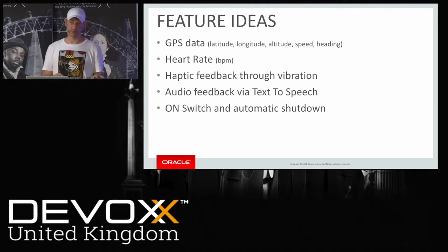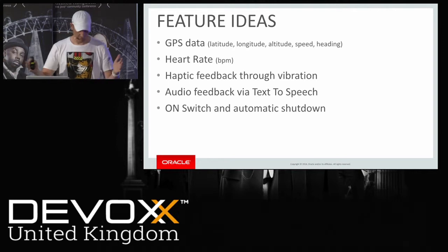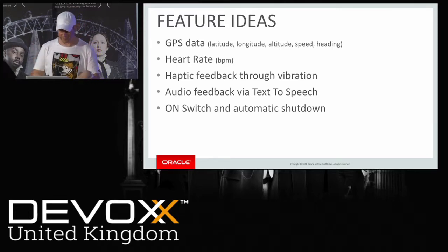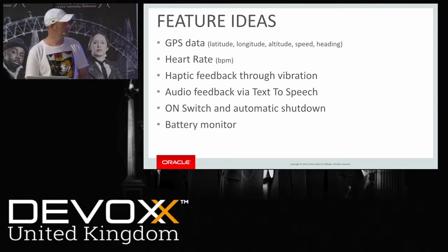So if you start with the Raspberry Pi, you will figure out it's not easy to switch it on and switch it off easily. If you switch it off like pulling the plug, then congratulations, the SD card is gone. And so this is all these things, if you don't think about it, you will stumble upon that problems.